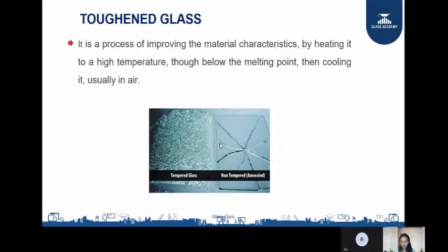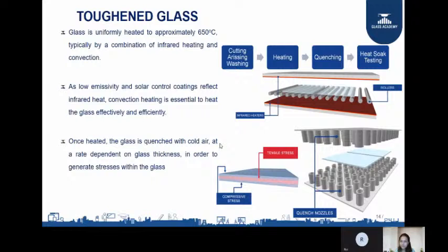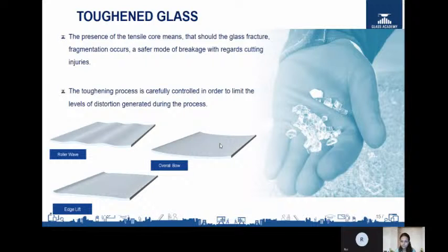And I think you saw in the slide where I showed you the raw material of the glass, it was written cullet. So cullet is nothing but a raw material. It is the broken pieces of glass, since when glass is manufactured, some glass will break, right? So cullet is that broken glass which you can reuse to manufacture new sheets of glass. So how will this cullet be helpful to you? First, you will have a saving in raw material. Second, you need less energy to melt, then less carbon dioxide emission, and less waste in the landfill.